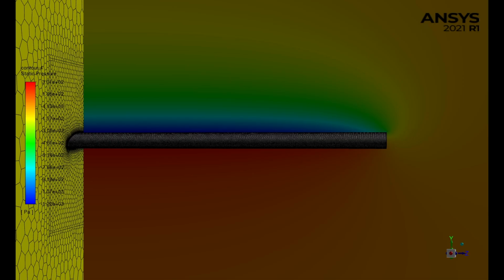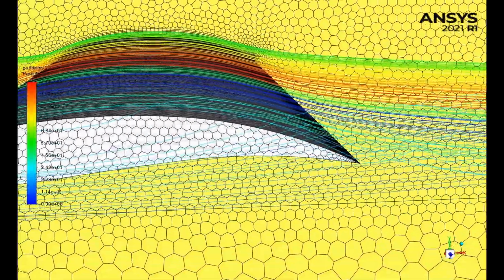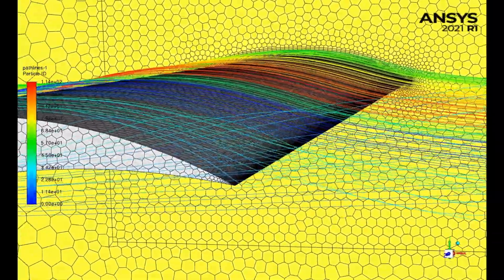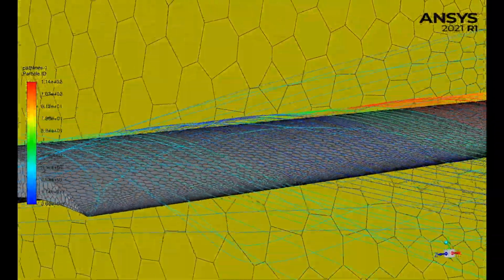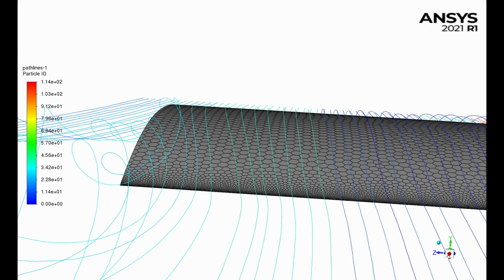This 3D effect is due to pressure equalization over the wingtip. We know we have high pressure below the wing and we have low pressure above. And this pressure difference causes airflow from the bottom of the wing to the top side, creating so-called wingtip vortices due to the fact that we still have a velocity component in x direction. When looking at the simulation, you can see exactly that. Path lines are plotted here, so lines that individual particles will take, and you can see that they go from the bottom surface and curve up to the top surface, then creating a swirl.